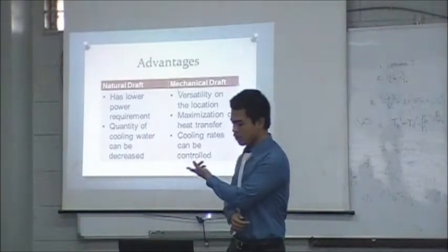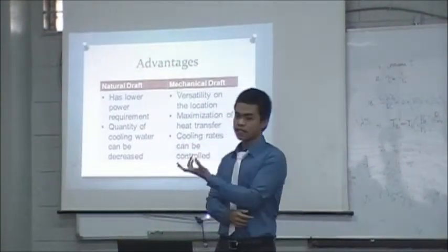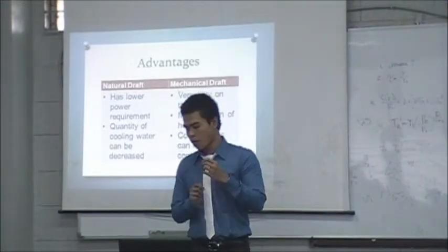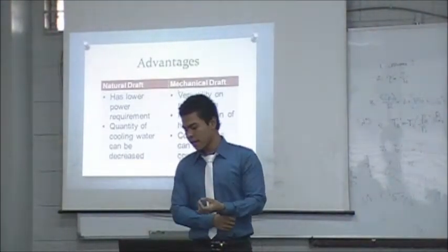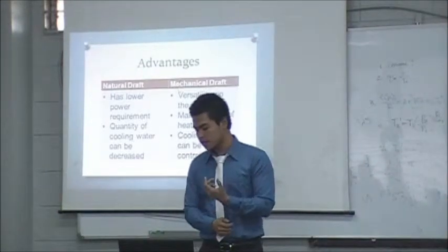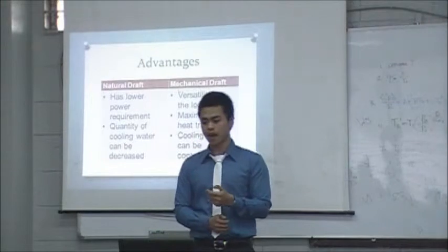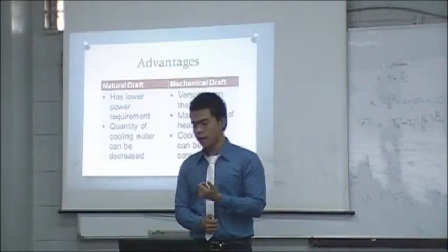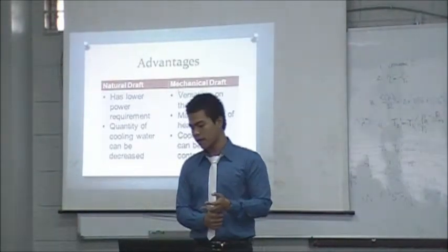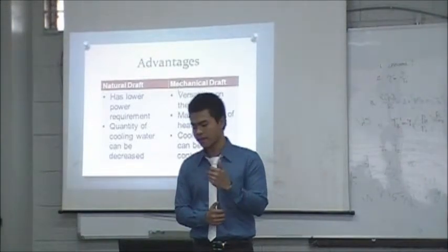For the mechanical draft, it is the versatility of location. Why is that so? Because it can be used in areas where the wet bulb temperature of air is high and exists over a long period of time. And it can be used in areas where power costs are minimal and there is availability of maintenance crews.